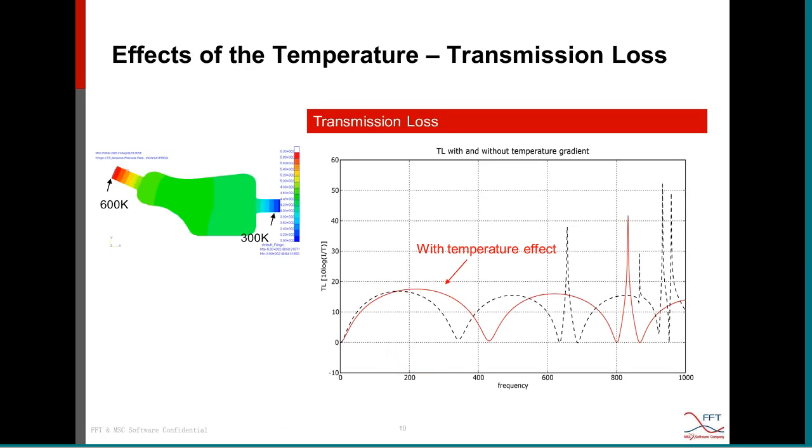Now this slide shows the difference of transmission loss on the same muffler between the case where we consider the temperature effect and the case where we just ignore that effect. We see that there's a significant influence by this temperature field, which is higher at the location closer to the engine, and the airflow cools down in the muffler when it goes out through the muffler to the exhaust outlet.